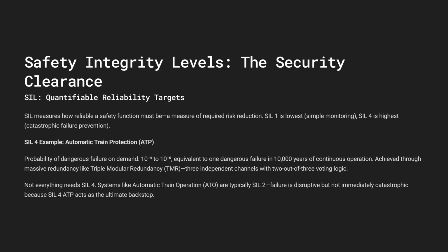You're right. You can't achieve it with just one simple component. It absolutely requires massive redundancy and diversity, proven through rigorous analysis like FTA and RBDs. So multiple backups. Multiple independent backups. We often use techniques like triple modular redundancy, TMR. You might have 3 completely separate computers or processing channels, all performing the exact same safety calculation using potentially diverse hardware or software. 3 doing the same job.